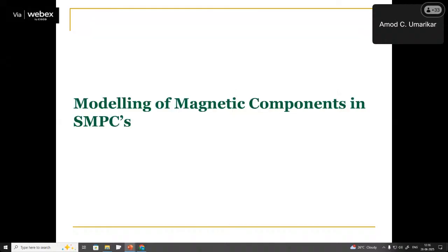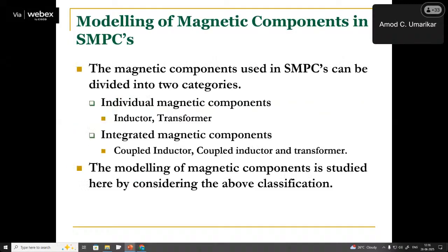This is the interesting part, modeling of magnetic components. This is really multi-domain. Now here, I'll take 5 minutes. How have you learned to model magnetic circuits? Which model have you used? With an inductor or any magnetic circuit, you have used the flux and MMF model, flux as a current, MMF as an effort, correct? Voltage.